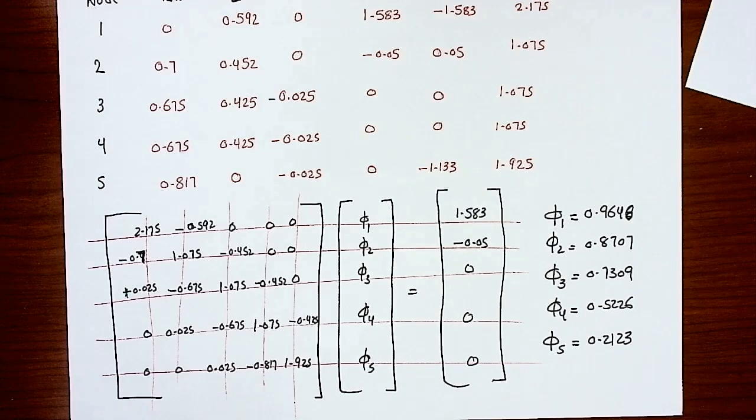So that's one thing to be careful about when you solve using the QUICK scheme. I know that has been a little bit of a long example, but it is very important to know how to apply the QUICK scheme. If you open your Star-CCM+ code that you use for numerical analysis, a CFD code with the finite volume method, you will find that the QUICK scheme already exists. Upwind scheme is also used, but the QUICK scheme gives us more accurate results for many reasons that we discussed during the approximation of that technique. And that concludes the recording for this example.